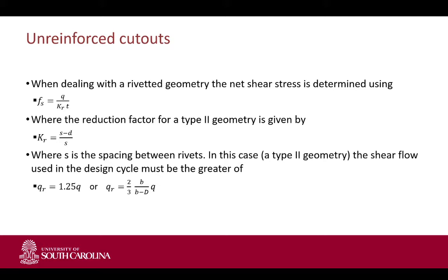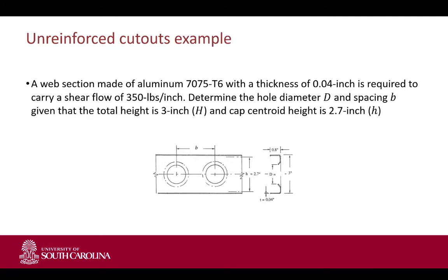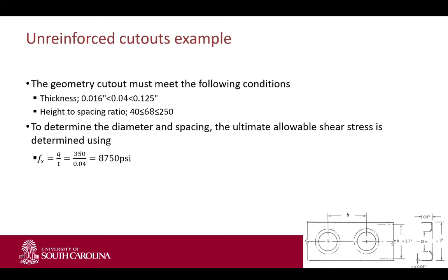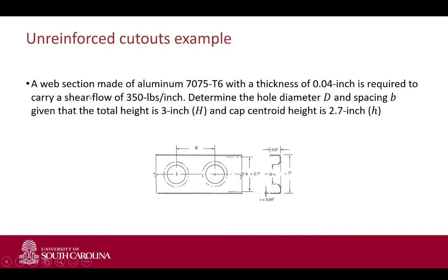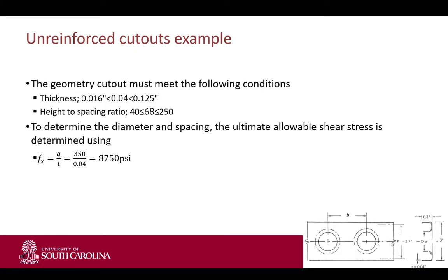I'll go through this a bit faster than I normally would, because I want to focus on the shear flows ourselves. Again, you can do a small example. It's already written down for you. It basically comes down to looking at the data that is available, the graphs, and seeing where your design falls in between. What is my thickness, what is my diameter, and what's our shear flow? The material and thickness are given, and the question is to determine the diameter and the spacing. So you have two variables, and you plug in the numbers that you already have.